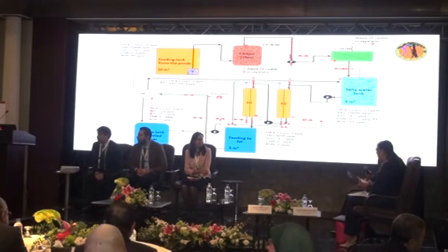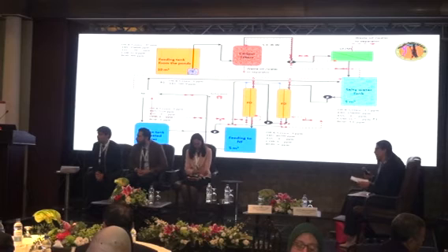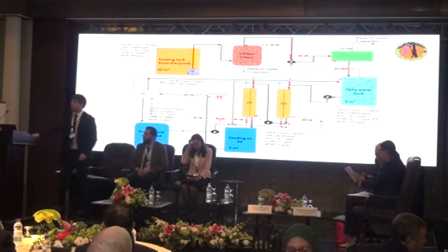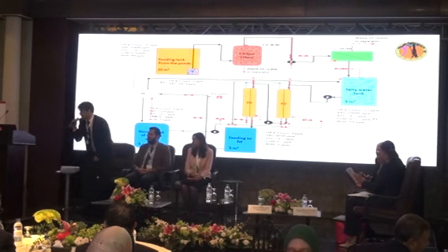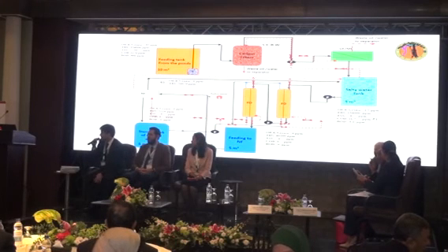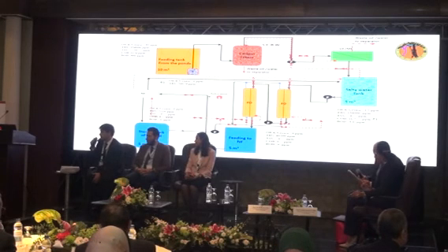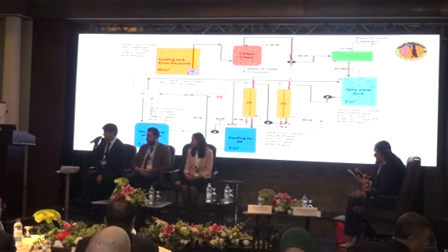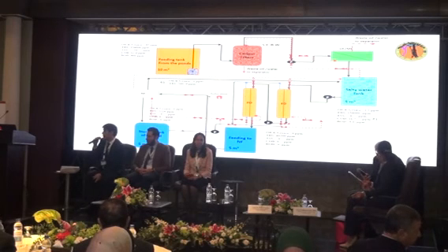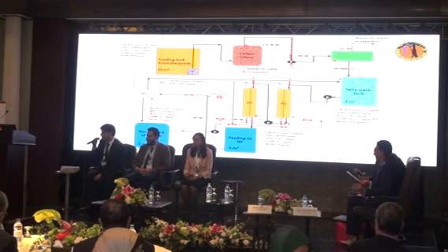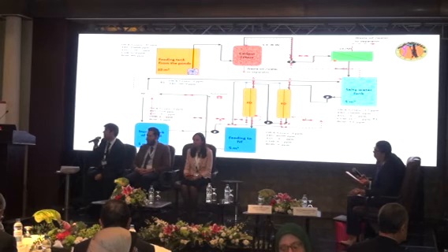Has this also been done for sour crude, or is this only for sweet crudes, these recovery units? It is possible also with sour crudes, but not all of them. You get limits and limitations, because you cannot remove all the sulfur with residue hydroconversion. However, you will still need diluent to make low sulfur fuel oil. It's a blending, according to the available fluids in your refinery.